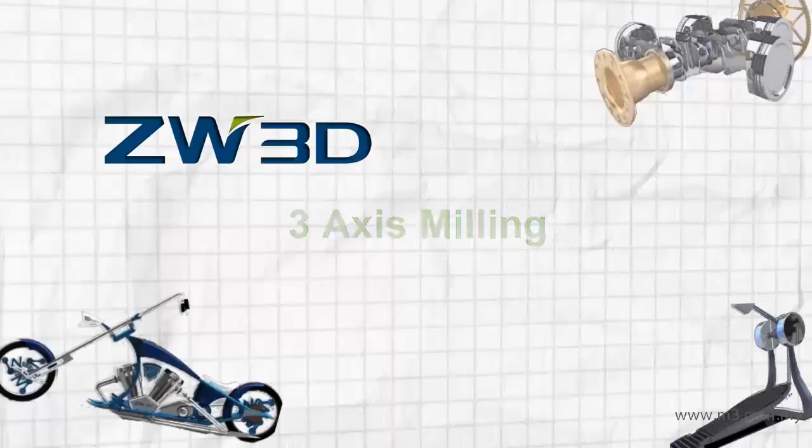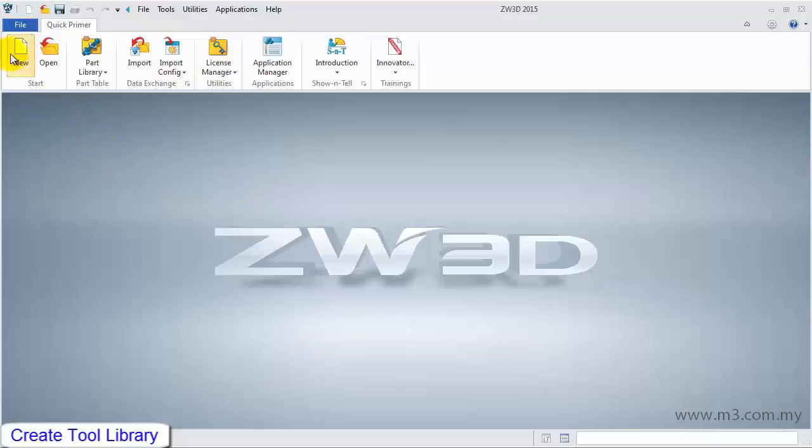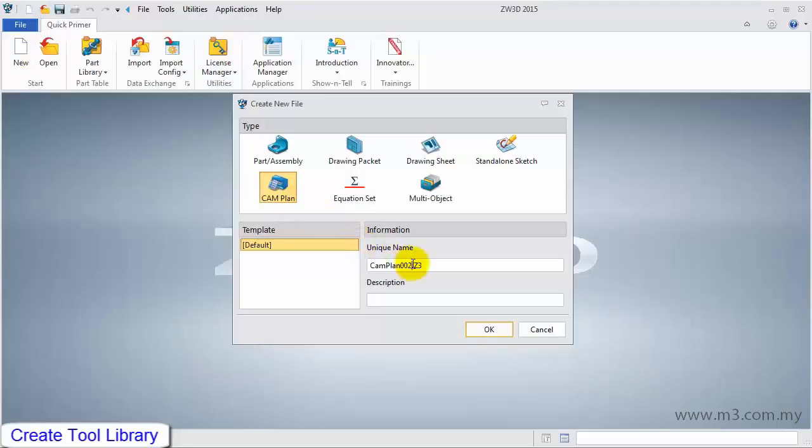Three-axis milling. In this video, we will introduce how to use the three-axis milling operation to create a toolpath, including how to create a tool library, define the reference operation, define limiting boundary, and so on. Now let's begin. Create a new CAM plan and name it Tool Library.